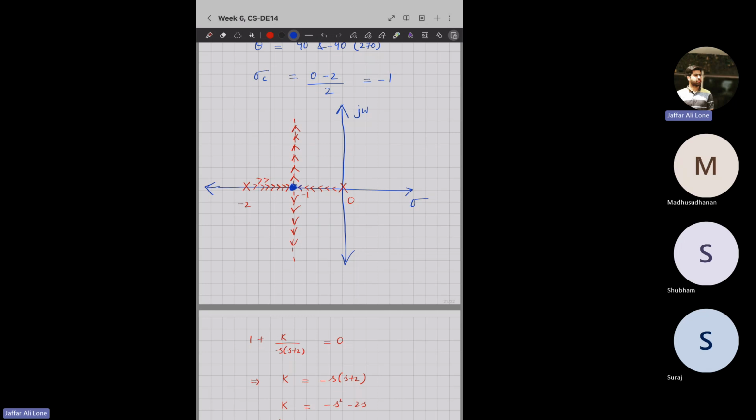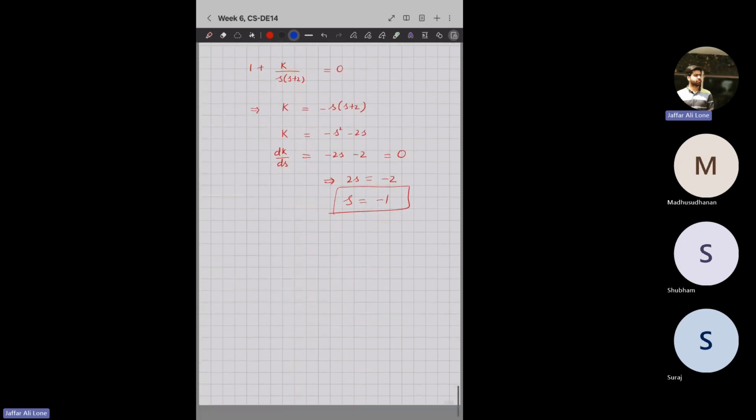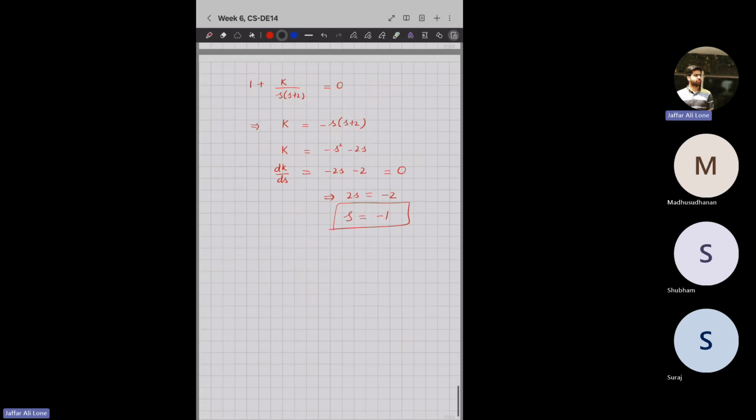But for the time being, I'm just concluding it here. Basically, we learned some of the rules of root locus, or how we can draw root locus: how to find centroid, how to find asymptotes, the number of asymptotes and their angles, and when breakaway or break points actually occur. This is basically the breakaway point. We will see something called the break-in point as well. But before I end today's lecture, we'll just discuss one thing: why this breakpoint occurs, right?